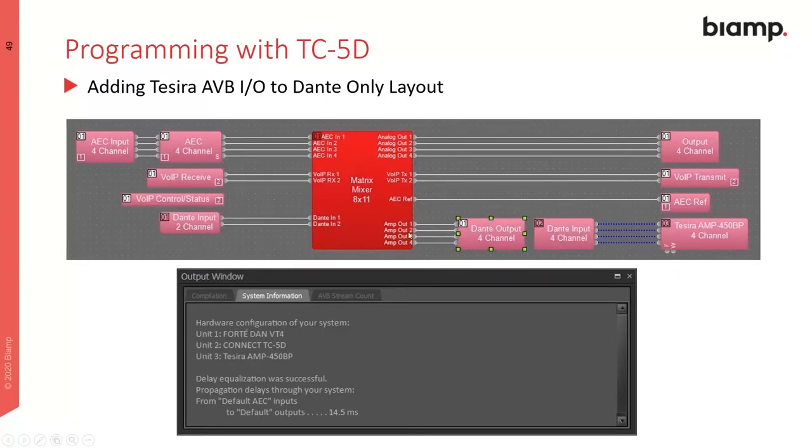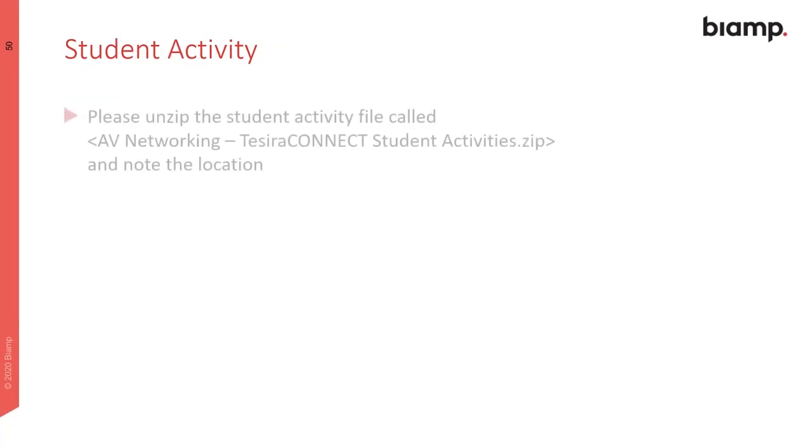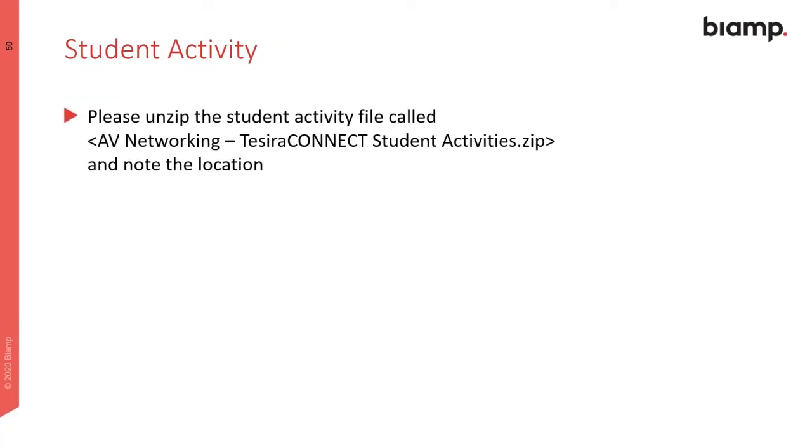But remember, this way it cannot work with smart devices, like the beam tracking microphone. Other AVB endpoints, it's doable. And this is because of the integration between the AEC and the beamforming between the microphone and the Tesira Forte AVB.